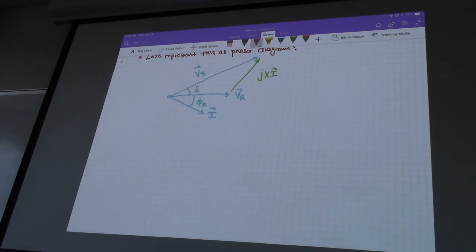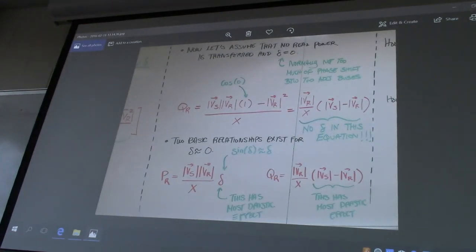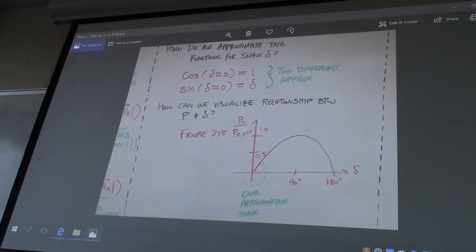We're going to be talking about, specifically for this simple transmission line example, how the value of the reactive element on the transmission line, which then plays into the power factor angle and the delta value between the phase shift along the transmission line, plays into the value of PR versus QR, and then going into this curve here, which is figure 218 from the book, and shows us